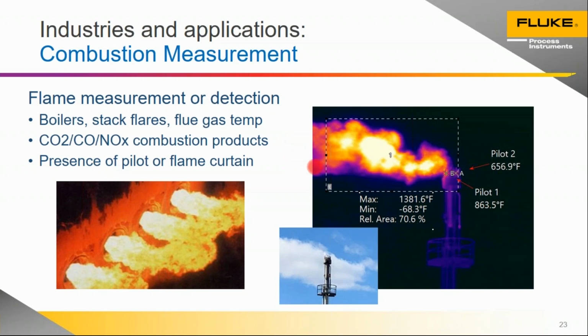In a similar application, we looked with a thermal imager. In this particular application, we were pretty far back here. We were about 400 feet away, we estimated, from this stack flare. The goal in this case, using a thermal imager, was not so much to know the temperature of that flame, but to make sure that we had the presence of flame in the right spots.